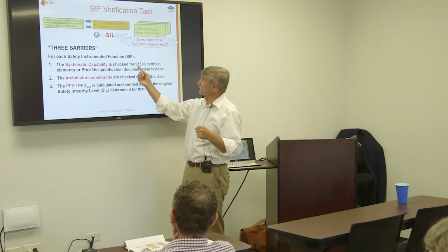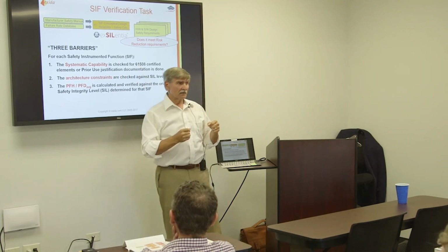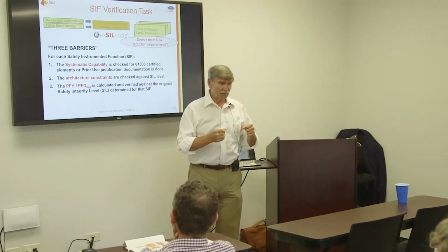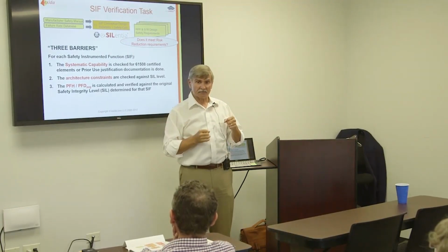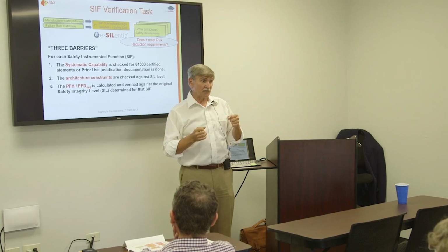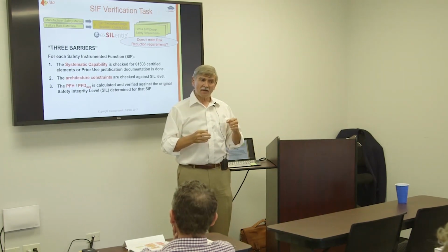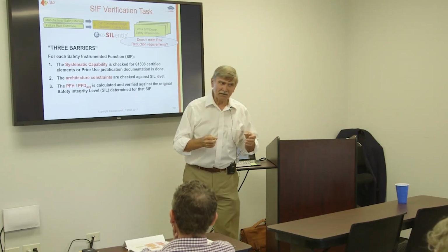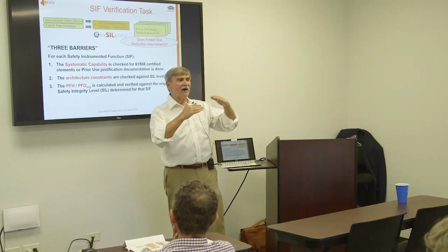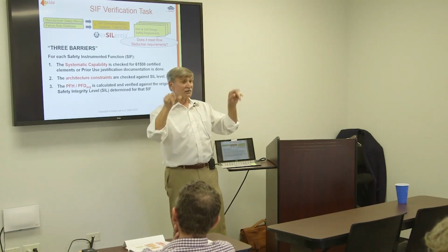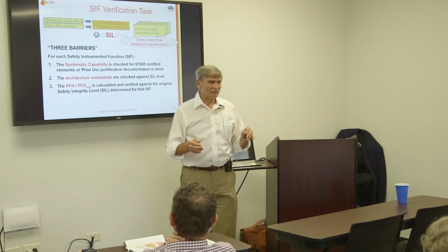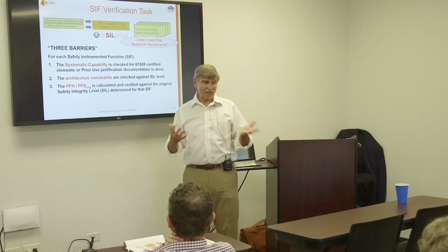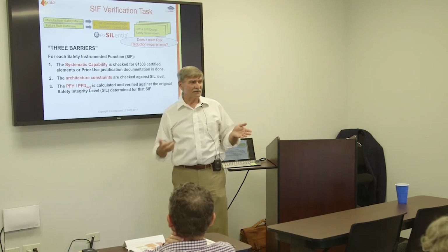If the product is certified, there should be a systematic capability rating right on the certificate. And it means you can't really use it in a SIL level higher than that unless you do some very special things. There is one exception clause, but for diverse redundancy.